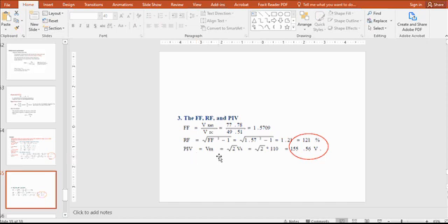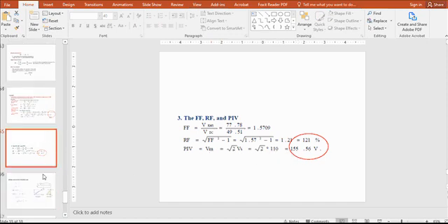And peak inverse voltage, we already discussed this in great detail in class. That is the maximum negative voltage which appears across the diodes. For the half wave rectifier it is the negative of this peak. So it is 155.56 volts.